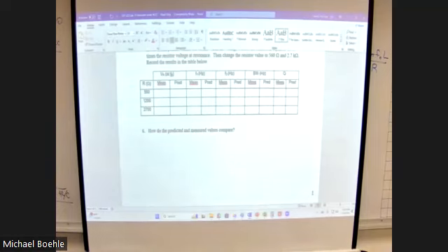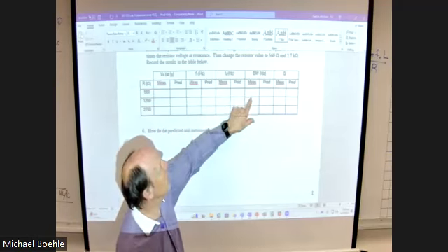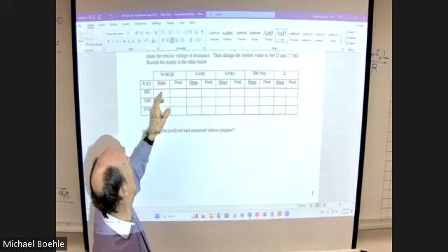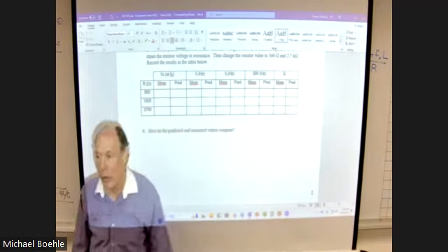You're going to lower the frequency until you get to that peak to peak. That's your lower cutoff frequency. You're going to raise it until it goes back up and then back down again. And when you get down to 0.707 of that maximum voltage, that's your upper cutoff frequency. Make sense to everyone? So you're going to measure those two, and then you just subtract the difference. That will be your bandwidth. And then you'll take that resonant frequency and divide by the bandwidth, and that'll be your Q.